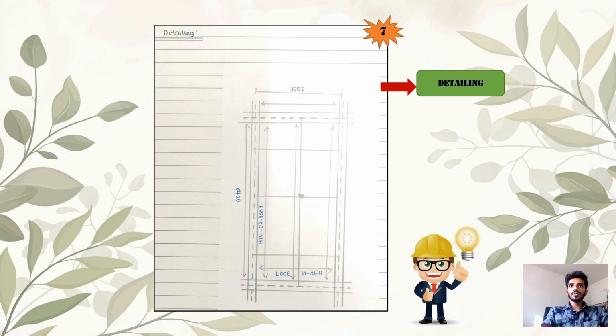So the width will be 3000 as per usual. So 3000 millimeters needs to be converted into meters. We will get 3.0 meters. So it's 6400 millimeters for the horizontal or even vertical distance, so 6.4 meters in order. So we have used the steel bars as H10-300 for the top, because it was at the top when we drew the diagram of shear force, and we are having H10-300 top. So we are going to use 300 top of the steel bars in detail, having a very strong one-way slab for the ground floor and also the first floor.